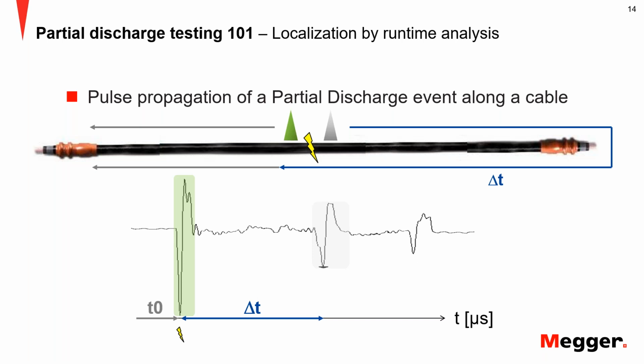So you get two reflections, the so-called first reflection and the so-called second reflection. And so you can think of this as a TDR, which you would initiate at the spot of the PD activity. That is the difference when you try to interpret these traces.